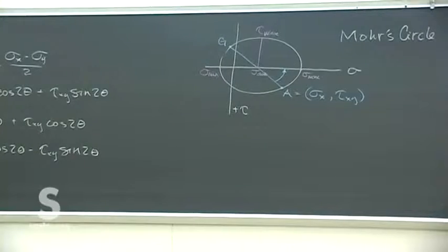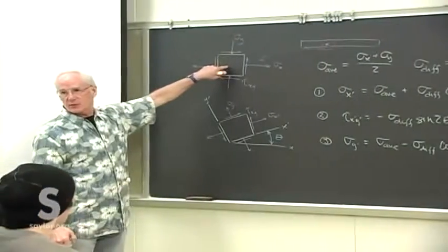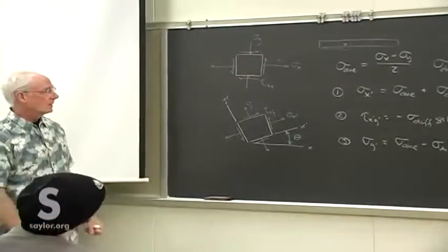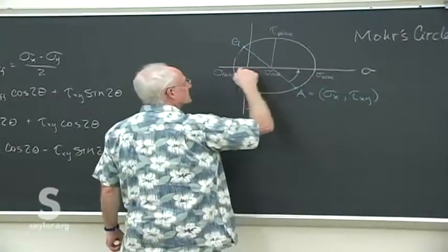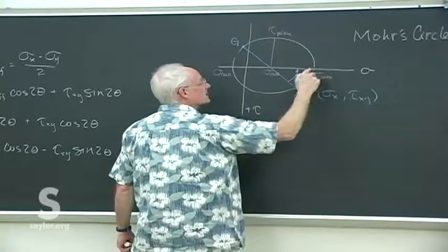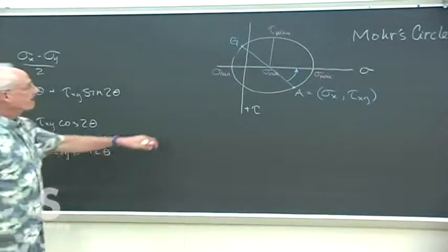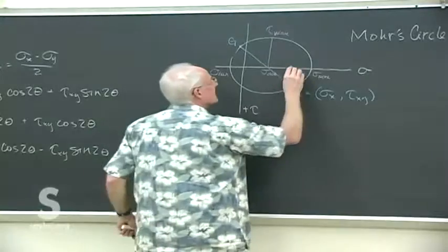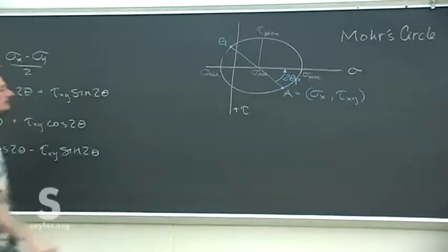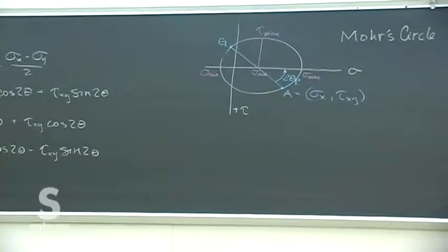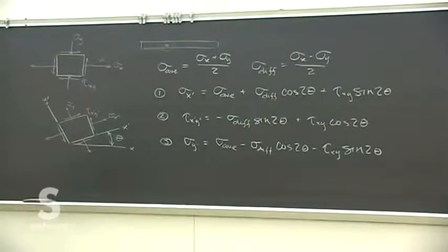We've defined a diameter with our original stresses in the untransformed state, just merely lined up with whatever the orientation of the solid was. But there's some angle that brings us back to this line here, brings us back actually to that point where we have the maximum normal stresses and 0 shear stress. And that angle was called theta p. And on Mohr's circle it happens to be 2 theta p, just because every angle in the transformed equations is a 2 theta angle.